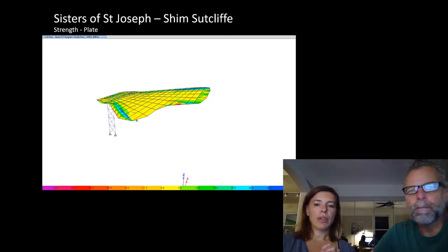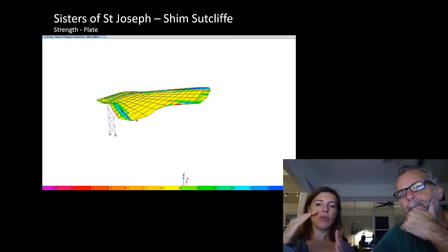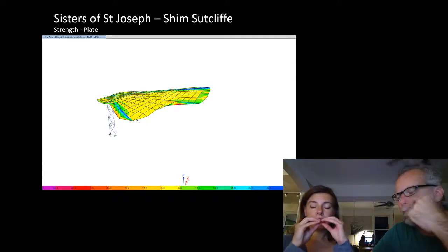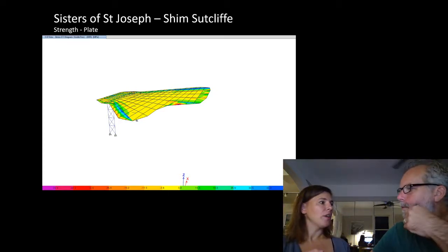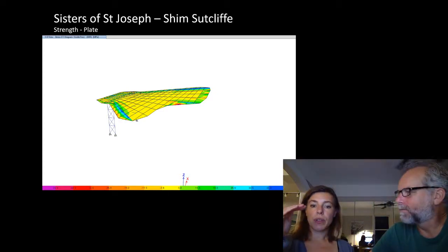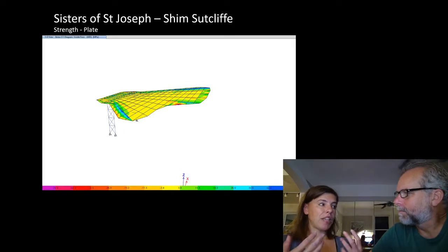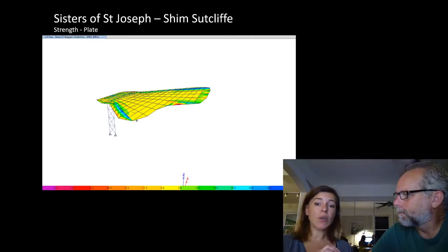Part of the way they make you treat that analysis is they make you look at how overstressed it is, or what the stresses are on it, and they give you a formula for how to reduce the capacity of that stress based on the thickness to length ratio, the flat width ratio, and you have to reduce the strength accordingly. Even though the strength of the steel actually hasn't changed, they compensate for local buckling by reducing the strength.